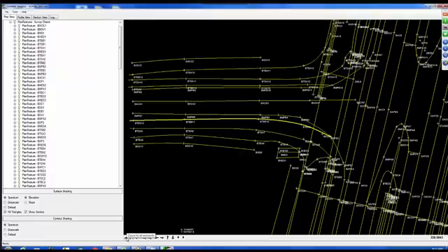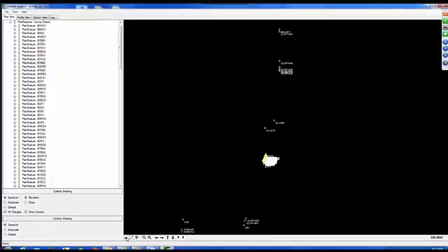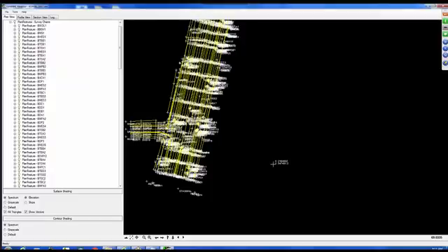So if I pick on that with my left mouse button, it's like doing a zoom extents. All right. If I pick the next option, zoom to dynamic, that's like the old zoom dynamic command in AutoCAD. Holding your left mouse button down, drag your box to the right and release it, and it zooms you into that area. Now, to the right of that command is a command called zoom recenter.